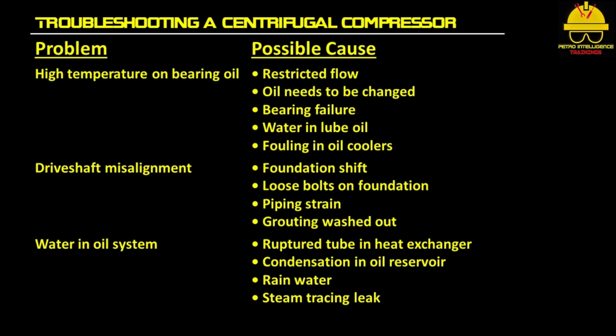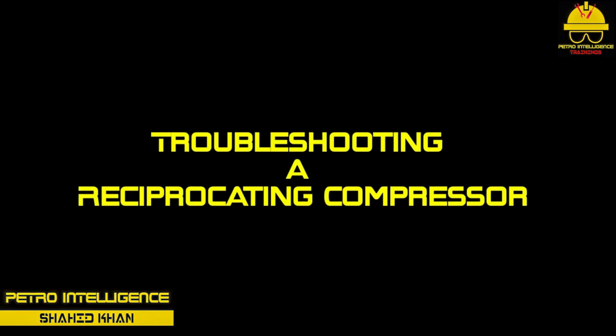If there is driveshaft misalignment, there might be foundation shift, loose bolts on foundation, piping strain, or grouting washed out. If there is water in oil system, there might be a ruptured tube in heat exchanger, condensation in oil reservoir, rainwater, or steam tracing leak.